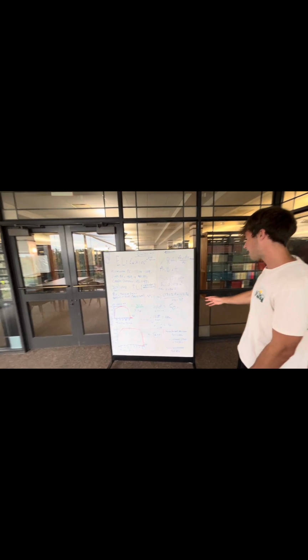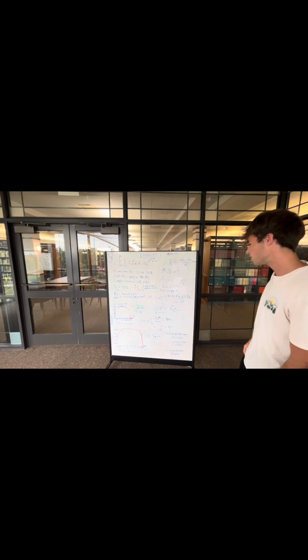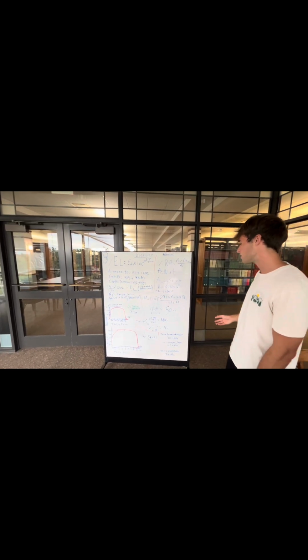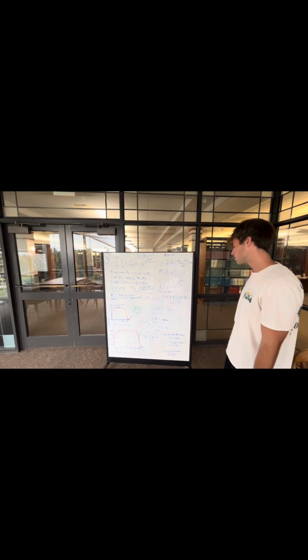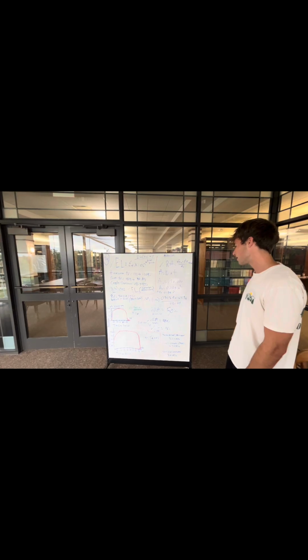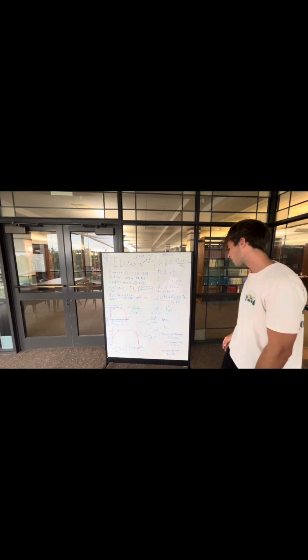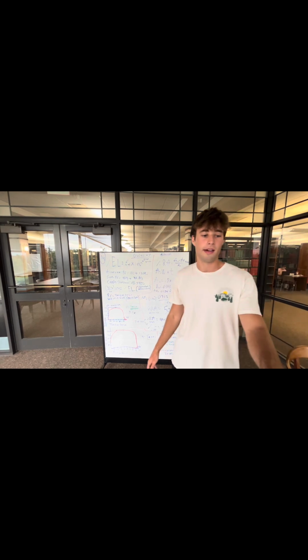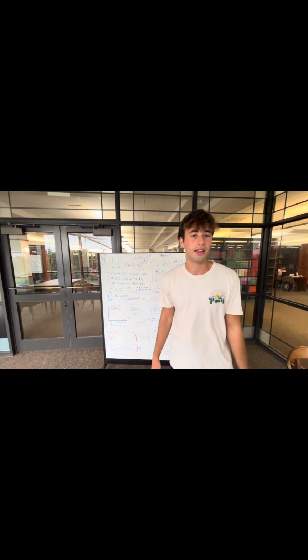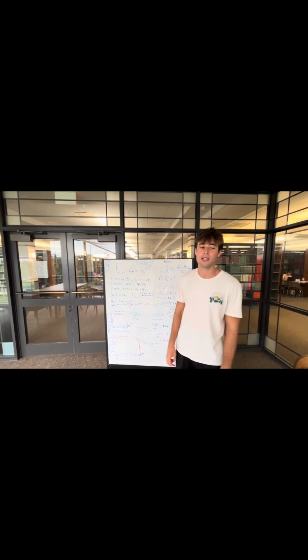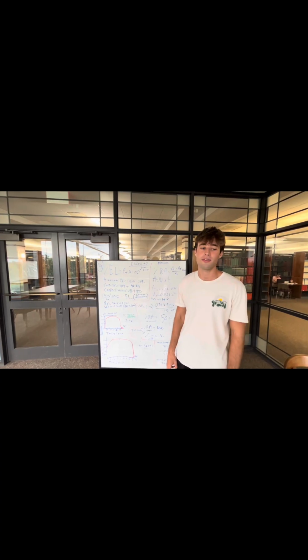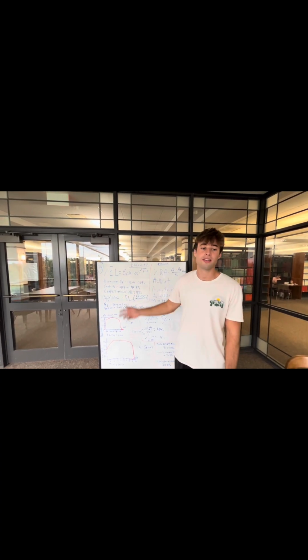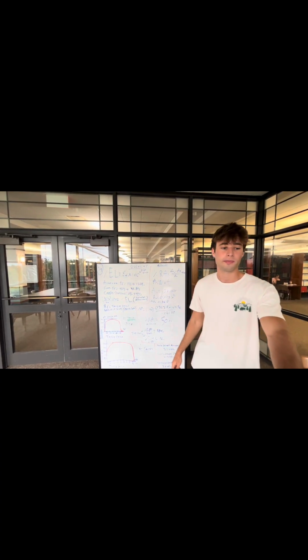Using the formula, we can determine that aluminum's reduced area percentage was around 50%. Your typical reduced area for steel is 44%, and for copper it is around 56%. Again, this percentage shows how ductile the material is. If it has a high percentage, it is more ductile, and if it has a low percentage, it means it's more brittle.